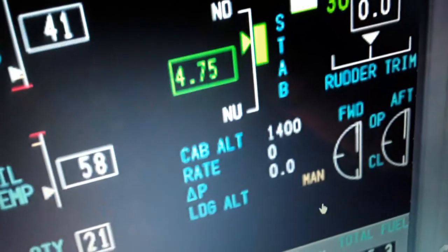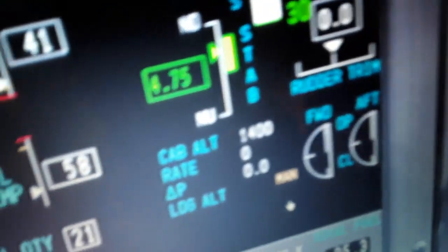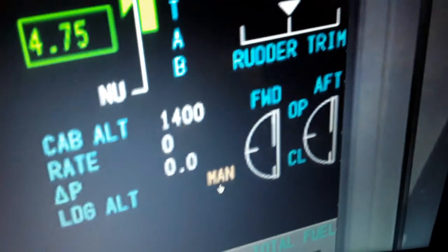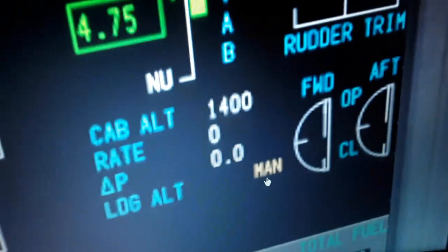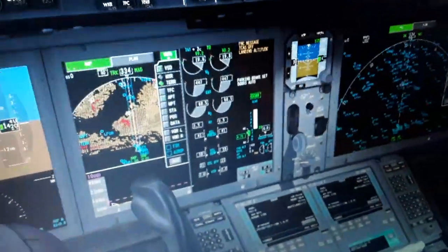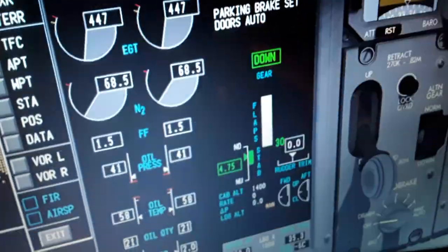And also the vibration of the N2 stage of the engine. So you can see the cabin pressurization also here, the outflow valves position for pressurizing or depressurizing the aircraft when we climb or when we descend. When we climb, we open and close the outflow valves to pressurize or depressurize the aircraft. They receive pressurized air from the engines, that's why it may be displayed here.